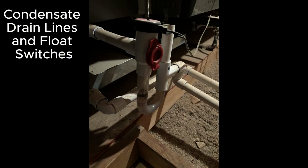And where this comes into play is something called a float switch, which is this right here. It's a P-trap with a 24-volt switch cap on the top. It's that black cap on the top. That will turn off the thermostat when it senses water is not flowing anymore through the condensate drain line. So that will turn off power to the thermostat. So if you have a thermostat that is going blank on you, a lot of homeowners feel like it's a problem with the thermostat, when in fact it's actually a restriction in their condensate drain line.